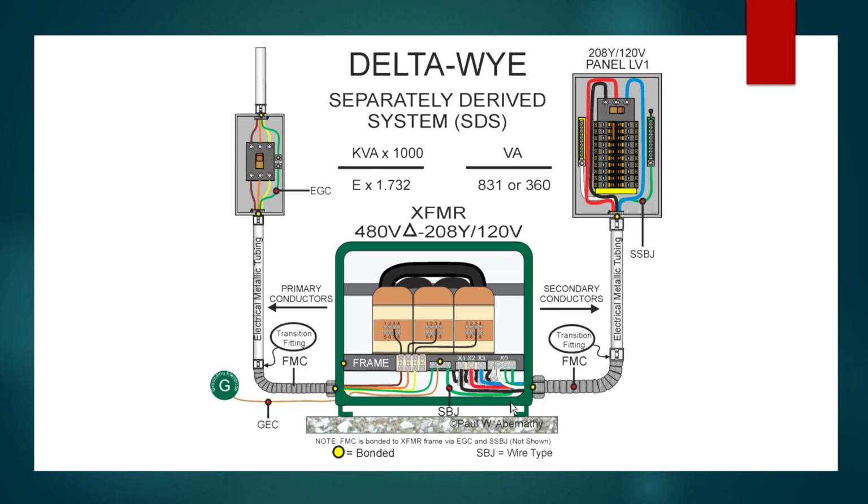And those rules in 240.21, tap rules and secondary conductor rules, are afforded us because there is no overcurrent protection right here. But if I did put it right here, then I could simply size the conductors that are coming out of it, feeders, based on whatever the load was going to be on those feeders, okay? So those conductors would be sized under the normal rules of Article 215 of the National Electrical Code, okay? 125% of the continuous, 100% of the non-continuous, and all those rules.